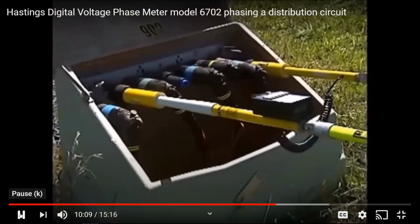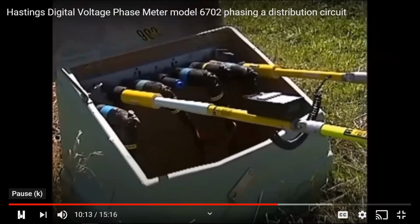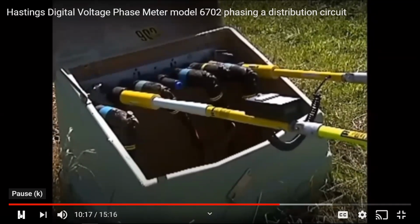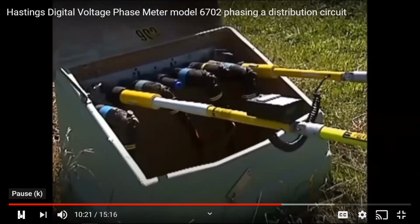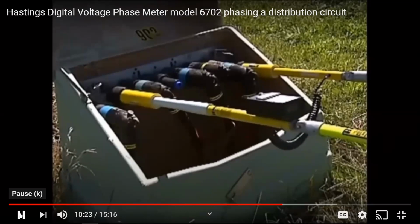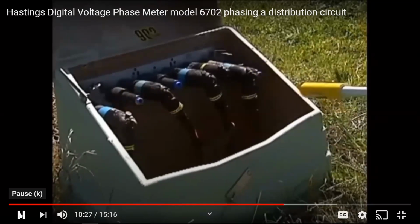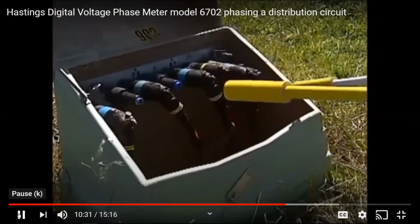Let's reverse our sticks and take that capacitive charge off that cable. It's real important to make sure that you're watching the meter when you plug it in, though. It truly is, to see that initial reading and then watch it bleed to 0. If you're not watching it, you wouldn't be able to pick that up. You would know if you had any current flow. Okay, well, bleed that. I'll trade you sticks, and go to ground.